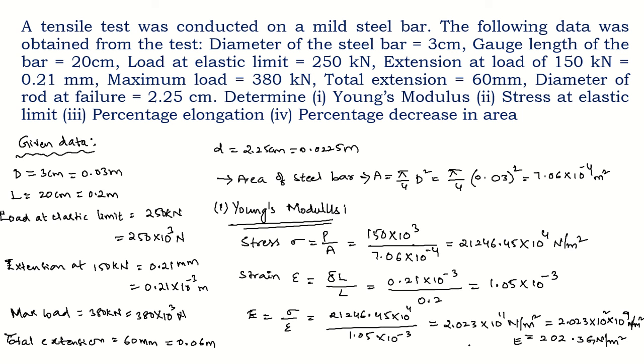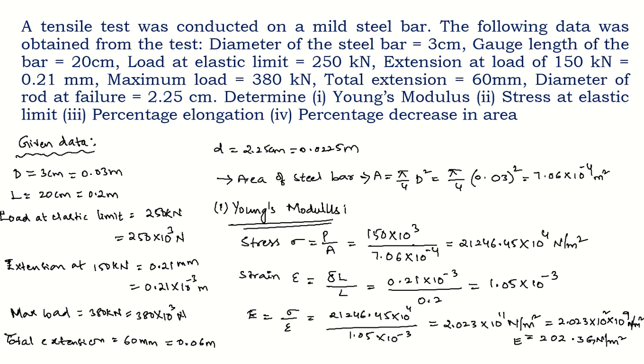Now we will see the second part of the question, which is stress at elastic limit. Particularly they are asking us what is the stress at elastic limit. So let's see. To calculate stress at the elastic limit, what should I know? I should know the load at the elastic limit by area. Is the load at the elastic limit given to us? Yes, load at the elastic limit is given as 250 kilonewton. By area, if I put capital A this value, I will get the stress.